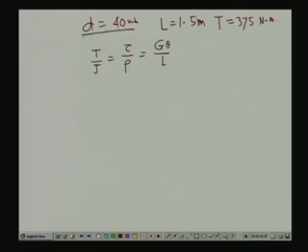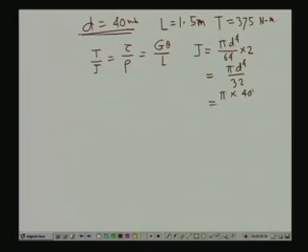Now, for the given bar, the polar moment of inertia J is equal to, now this is pi d4 by 64 is Ix and also Iy is pi d4 by 64. So, Ix plus Iy, twice of that, is equal to pi d4 by 32. This is the polar moment of inertia, and d being 40, this is equal to pi into 40 to the power 4 divided by 32 millimeter to the power 4. So, this gives us a value of 2.513 into 10 to the power 5 millimeter to the power 4.